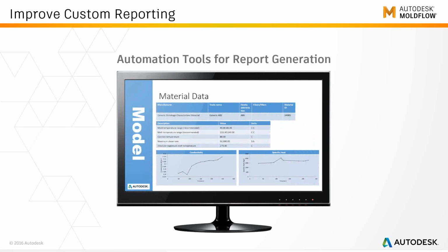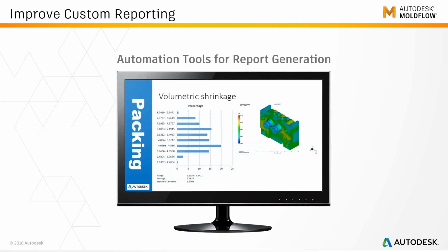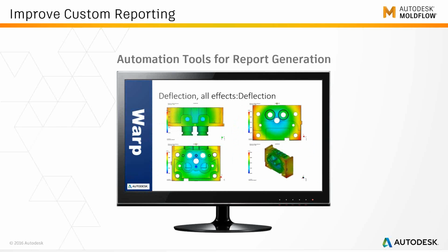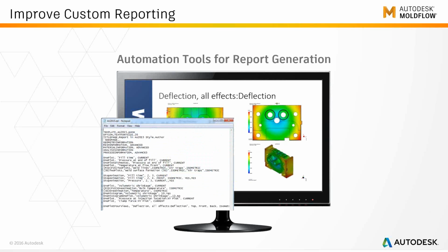We also created functionality to populate tables easily, such as tables of material data that automatically get extracted from the screen outputs. We have created tables inside of PowerPoint that are histograms, something the Moldflow user interface doesn't provide right now, as well as warpage deflection plots in isometric form. And this is all driven through very simple scripts.